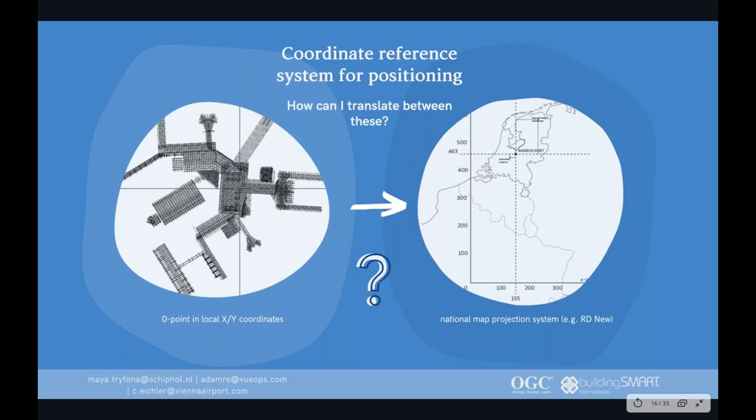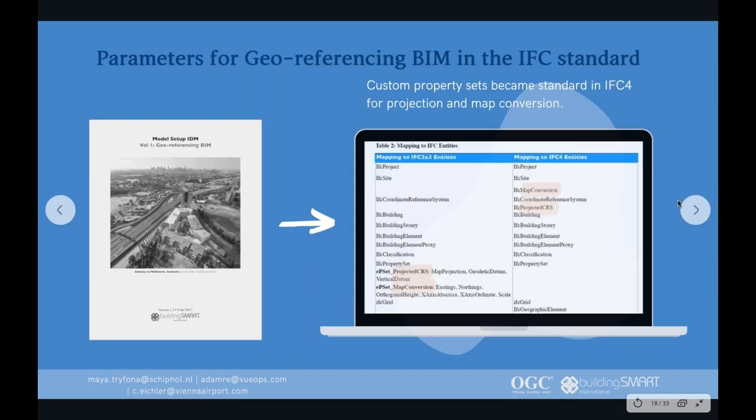So in the next slide, to make the previous transformation in large sites like airports, the curvature of the Earth could play an important role. So, for example, airports like Schiphol have a very large site, more than 3 kilometers. Therefore, we really need to make the transformation, but taking into consideration few more parameters.